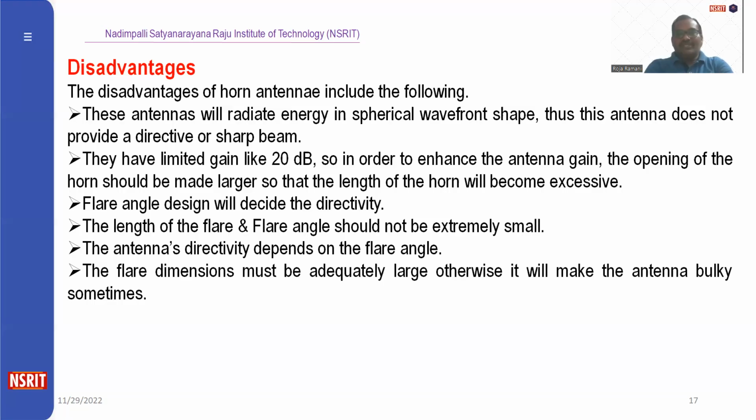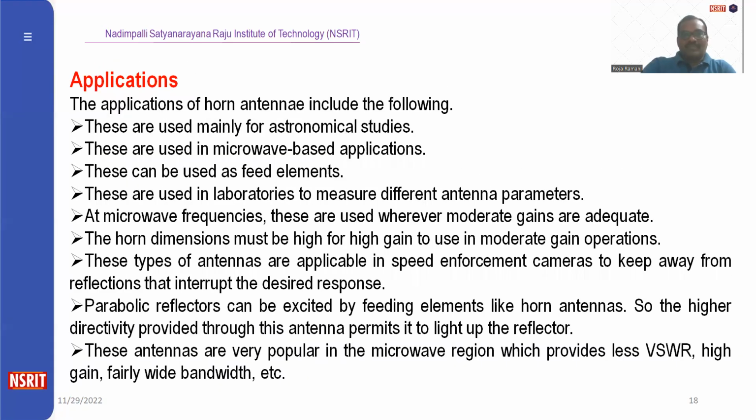Flare angle design will decide the directivity. The length of the flare and the flare angle should not be extremely small. The antenna's directivity depends upon the flare angle. The flare dimension must be adequately large, otherwise it will sometimes make the antenna bulky.